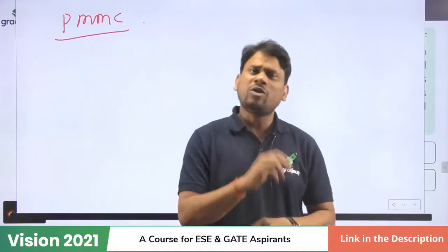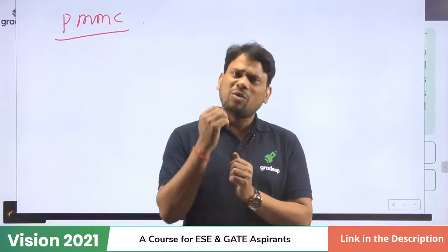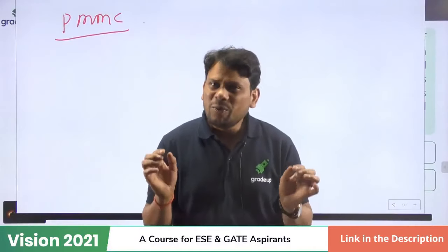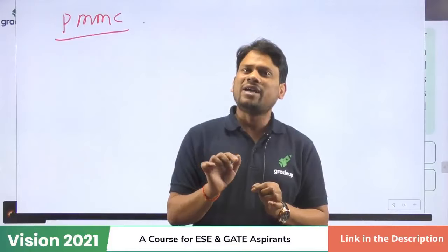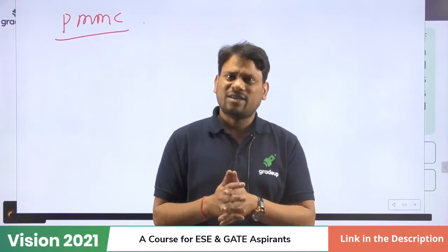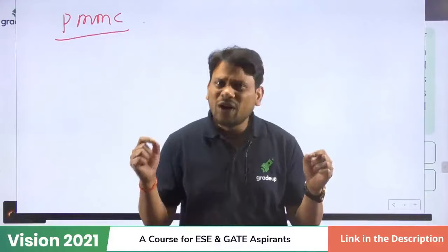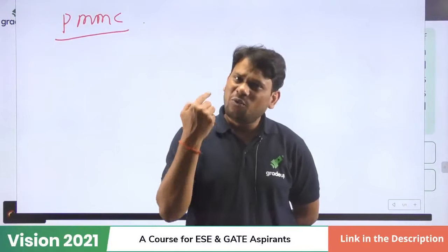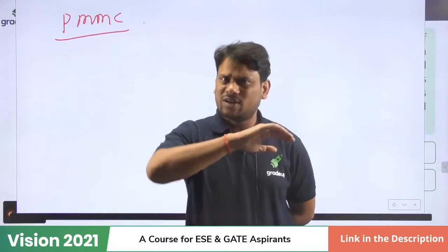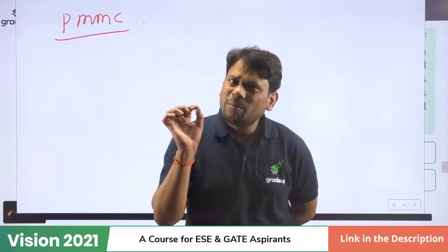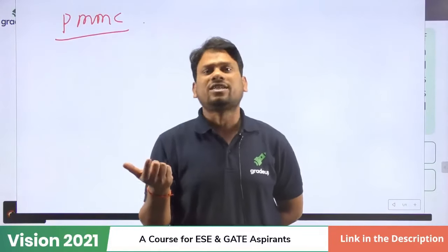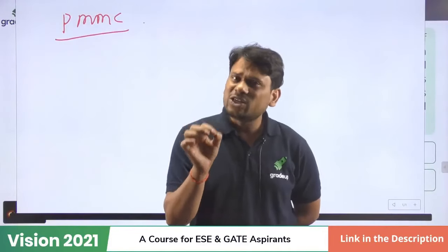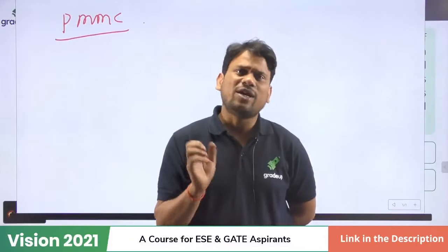place one moving coil. We will discuss the concept of moving coil sometime later. What do you think about the permanent magnet? If we provide AC supply to it, then the resultant torque, then the resultant power, whatever, will always be 0. So please try to understand, PMMC always provides, for GATE point of view, an average value of AC signal 0. I repeat, average value of AC signal 0. So that's why it is not suitable to measure AC quantity.